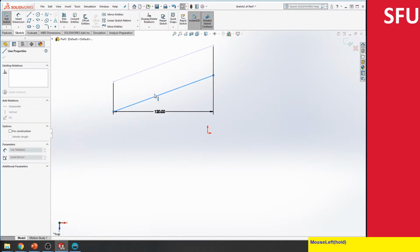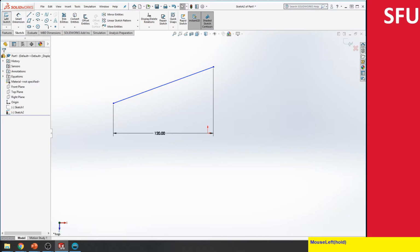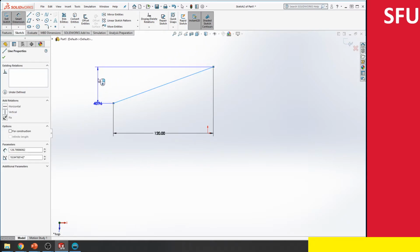What I can also do is move the line here. I can put a smart dimension, and then I can do a vertical constraint, which will fully constrain it and define all the lengths. I can also fix the length of the line itself, but I need to make sure that I move parallel to the line. If you have an issue, you might have to move the mouse a couple of times until you get the dimension to be parallel to the line.